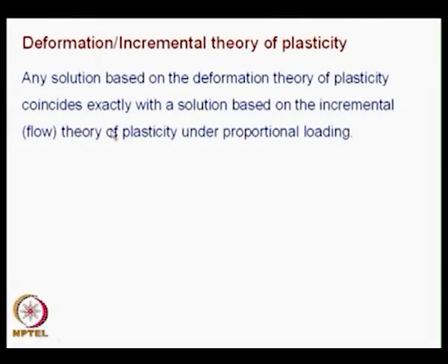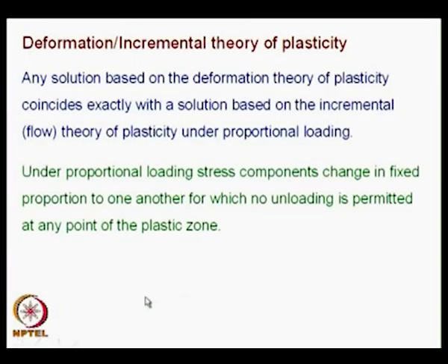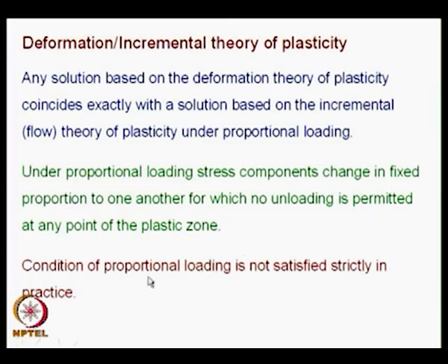So, that is how the story goes, and under proportional loading stress components change in fixed proportion to one another, for which no unloading is permitted at any point of the plastic zone. That is a key point. We have already seen what is the kind of complexity when you have unloading. So, in proportional loading you ensure that no unloading is permitted, and this also you have to keep at the back of your mind.